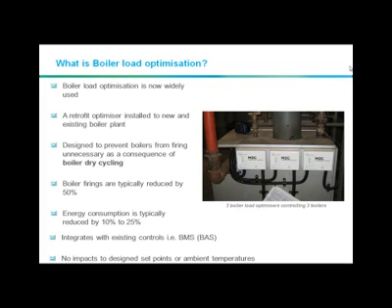Clearly, any retrofit control must fully integrate with the existing controls, as mentioned, with building management systems and BAS systems. There is nothing worse than having two systems conflicting with each other, so it's vital that these systems integrate and complement each other. And another aspect of this is that any retrofit control mustn't impact on the design set points or the ambient temperatures or comfort levels of what this plant is actually serving.